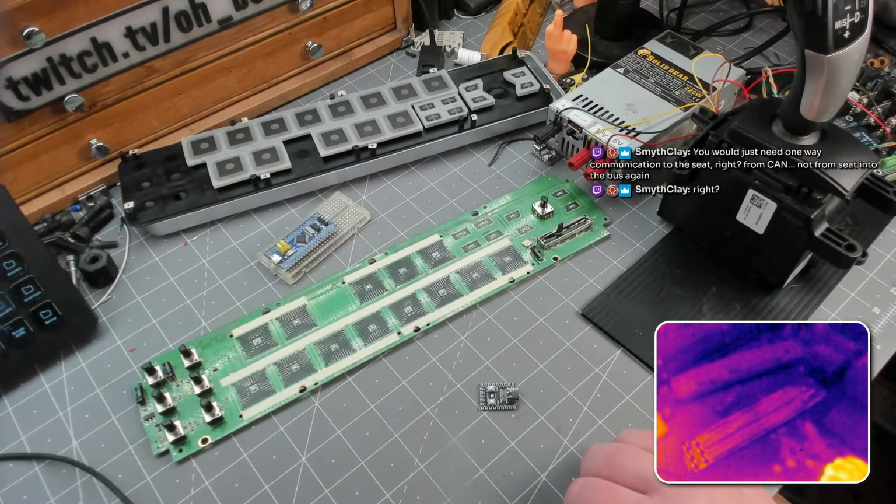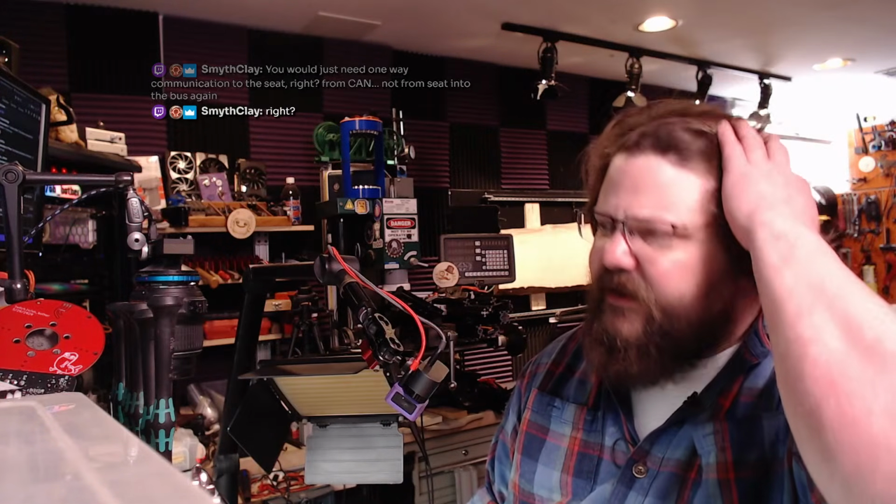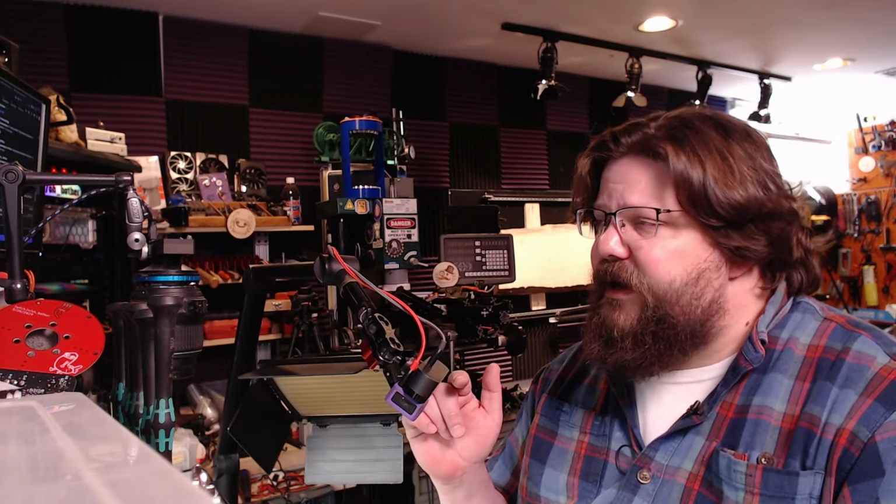You just need one-way communication to the seat, right? From CAN? Two-way. I think it needs two-way, because it's a keep-alive signal, and then it relays stuff back. We don't necessarily need to listen to what's coming back, so I could potentially use the Raspberry Pi with CAN bus to try to inject a signal into the chair. But I think we measured the waves that are coming back on the data line, and it looked like it was 100 kbps instead of 5. I really hope it speaks 5, but I don't think it does.